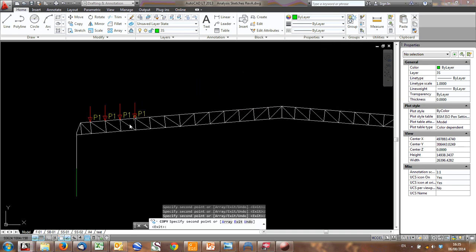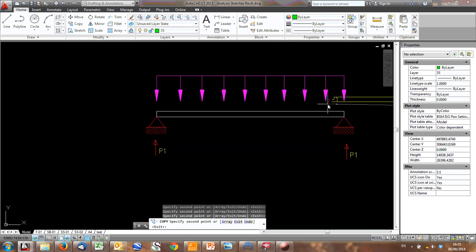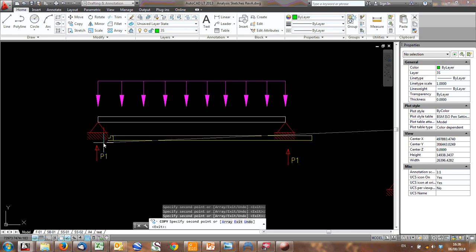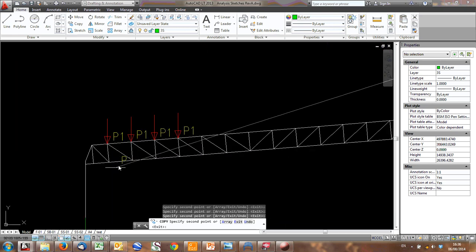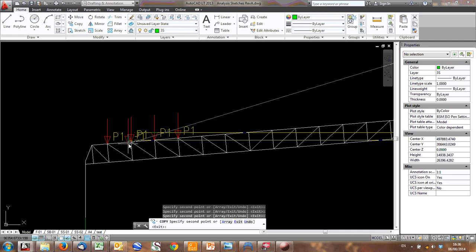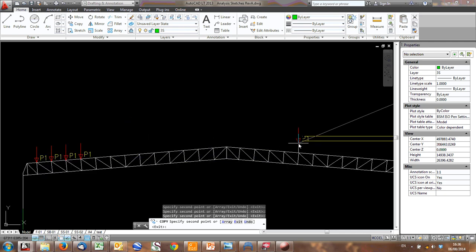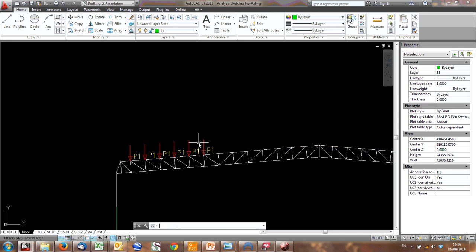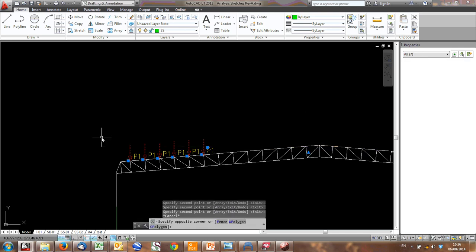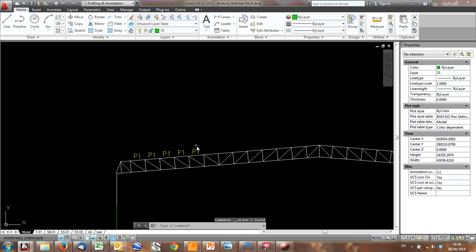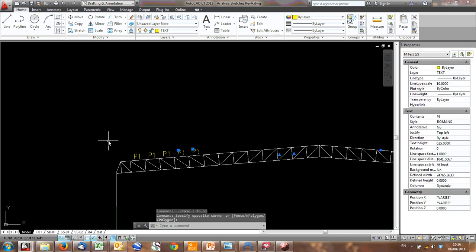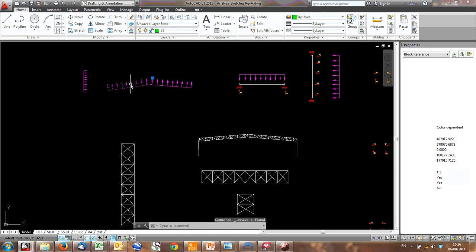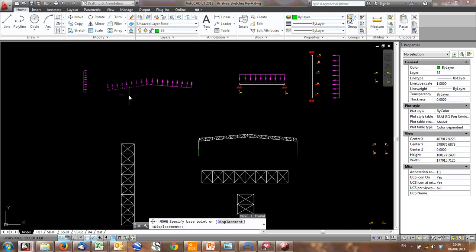And that is the way you can start sizing it, because what you do here, you analyze it with a live load, and you get a reaction, and a dead load, etc., etc. And suddenly you have a load that you can apply there. You can apply those all the way along. With this many point loads, though, what you'll find is it almost approximates out to a uniformly distributed load. So, you have to be careful doing it, because it's an approximation of all these point loads, but you could otherwise provide a UDL all the way along.